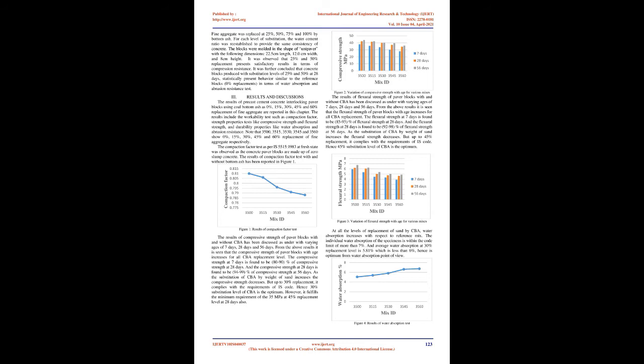The compaction factor test as per IS 5515:1983 at fresh state was observed as the concrete paver blocks are made up of zero slump concrete. The results of compaction factor test with and without bottom ash have been reported in Figure 1.